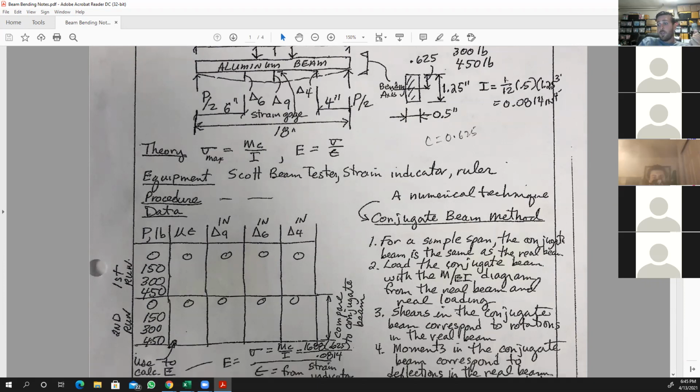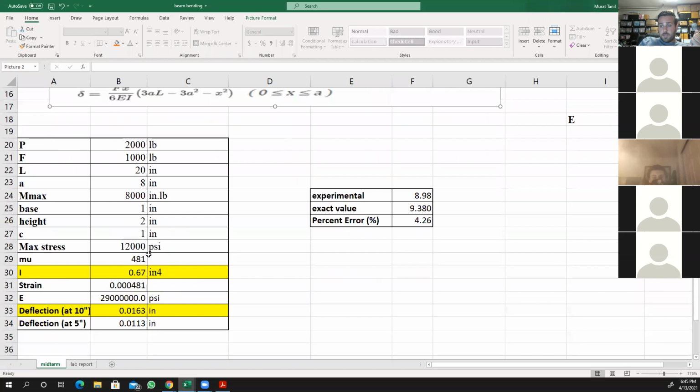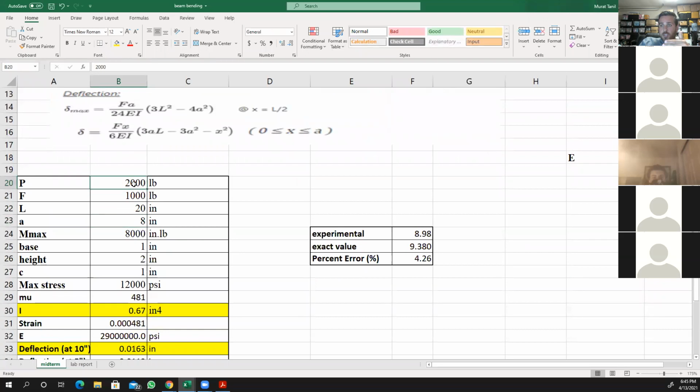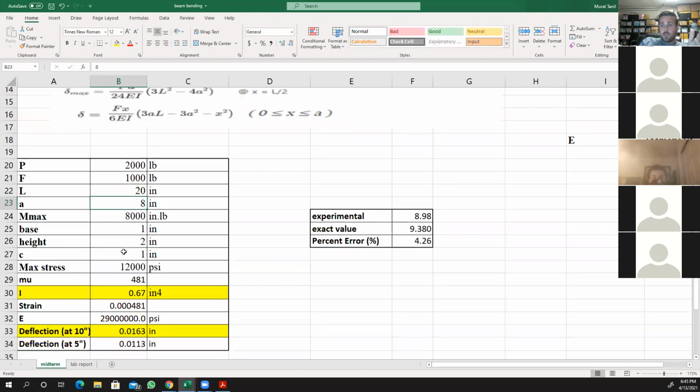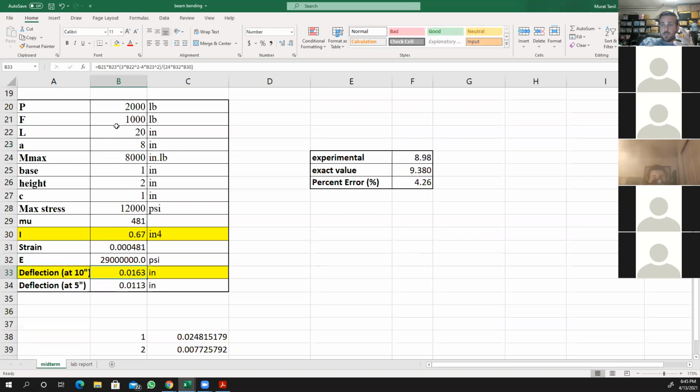That takes time. Either you're going to use a spreadsheet that gives you the deflection at certain locations. Usually the maximum deflection governs. You want your maximum deflection to be less than whatever is prescribed by the American Society of Civil Engineers. The only variables you can change are the applied load and the length of your beam. You can change the orientation of the beam to reduce the deflection. What parameters can be adjusted? That will be your job.